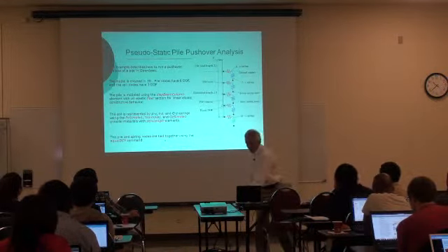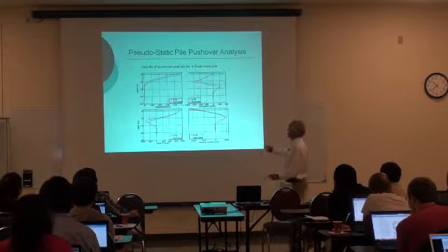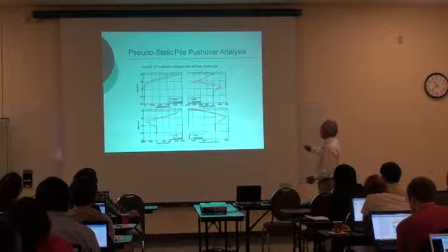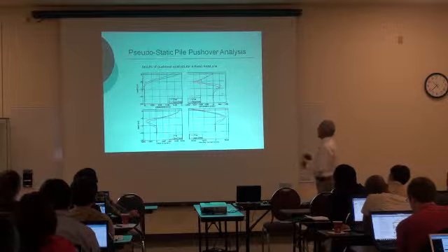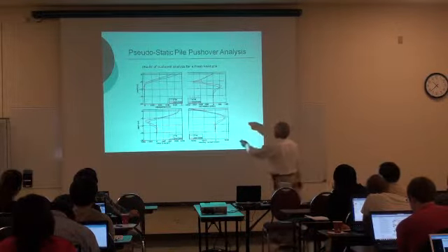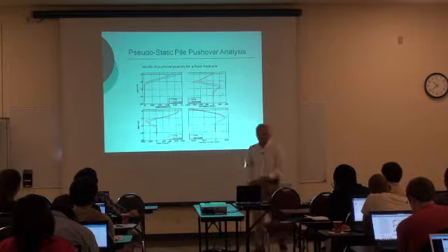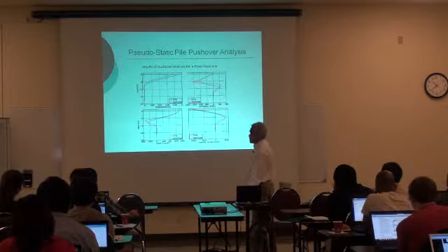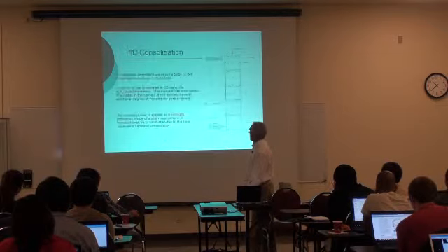models. And what we did is compare the results in terms of displacement, the soil reaction, and the shear and the bending moments with another tool like LPile to see if we were getting results that were more or less similar. You can use that script, it's available.